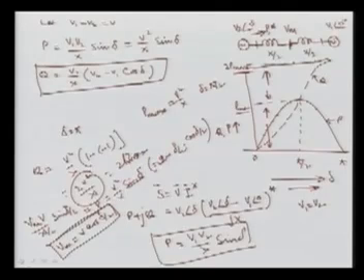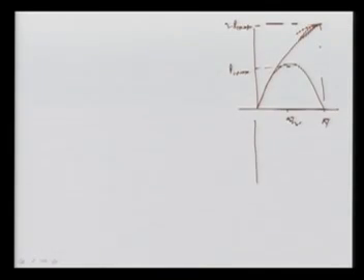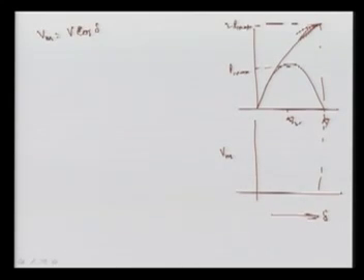And if we are going to draw the graph for this, we will get this V cos delta by 2. Means if you are going to draw this, I am drawing here your midpoint voltage Vm, this is your angle delta. Now I am going to draw this Vm, it is nothing but your V cos delta by 2. When delta is 0, V is the value, that is 1 per unit here. I can say this is 1, or you can say V here simply.